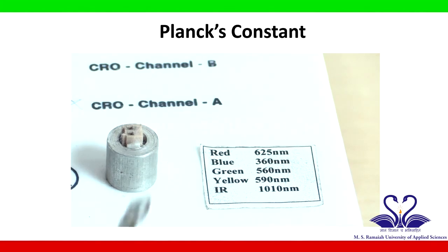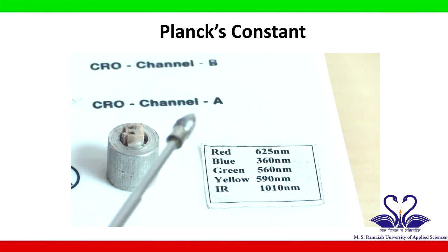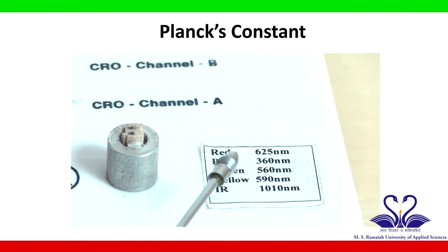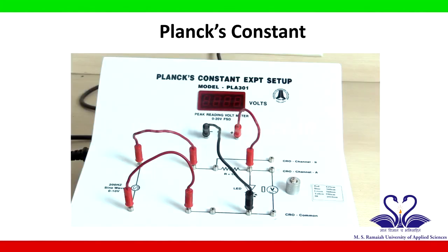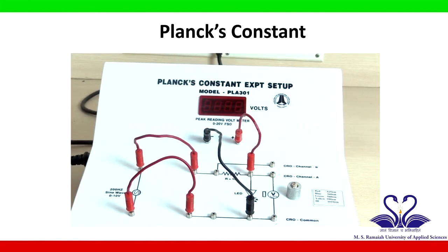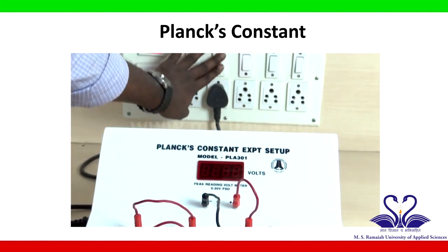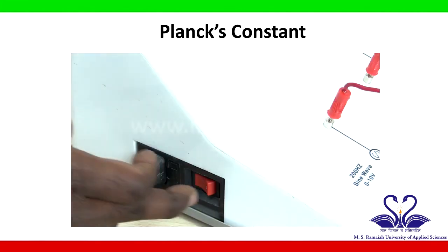In this experiment, we will be using LEDs of red, blue, green, yellow and IR wavelengths. In this experiment, we measure the knee voltage for each LED. We will begin the experiment. First of all, switch on the source and switch on the apparatus.